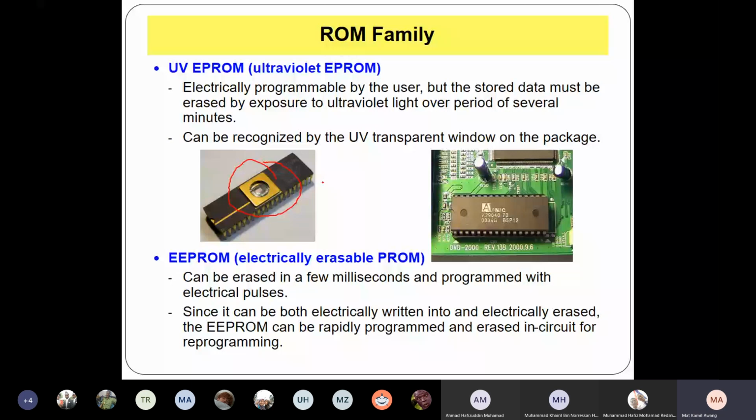you expose the IC inside. Actually, this is really the real IC, the real semiconductor, even though this is the size. This is the size of the package, but the real semiconductor is this, the small square inside there. So this circular opening here is made of glass, to allow the UV light to erase whatever is in the semicon here.